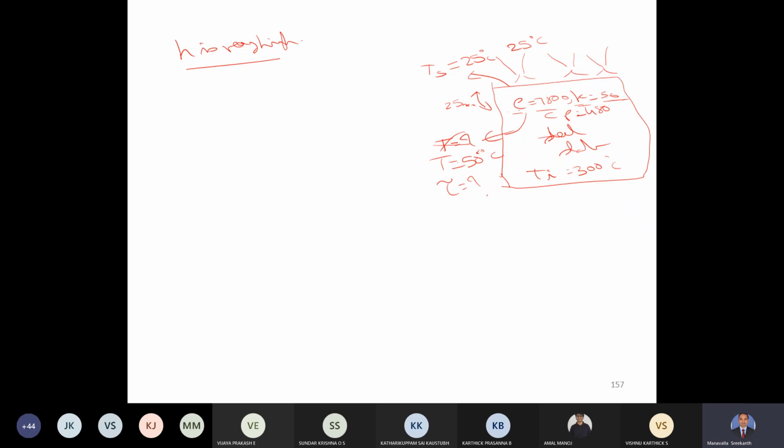Now open page number 67. All of you open page number 67 in your data book. In your data book, the first one, you see surface temperature suddenly changed and maintained constant. This is the case for a semi-infinite solid. So initially the surface temperature was at 300 degrees Celsius. With this jet of water at 25, it suddenly changed to 25 degrees Celsius and is maintained at 25 degrees Celsius. So what is happening? This slab is cooling and we have to find how long it takes to cool this depth of 25 millimeters to reach 50 degrees Celsius.